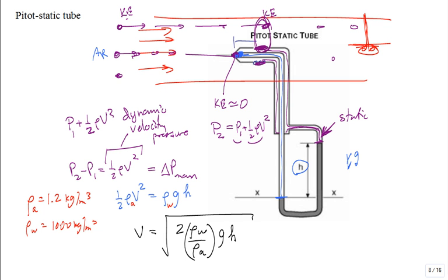Any other comments? So why does the opening have to be small if I don't see anything in the equation for the area? Oh, well, we do know that the probe has really been an obstruction to the flow. And so if I look at it, maybe I'm having a square duct. I don't want to put a pitot static tube of this diameter in the square duct. It really needs to have a small cross-sectional area because it is blocking it. But it's blocking it as such a small fraction that I can use the approximation of Bernoulli's equation to get a correlation to predict the speed.